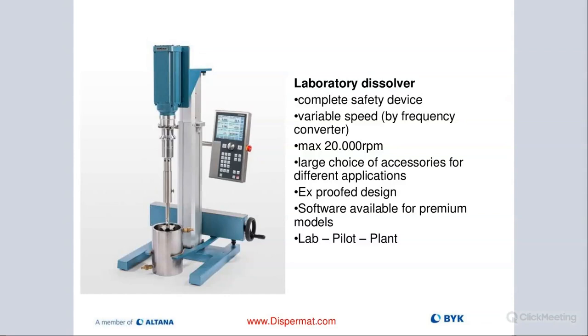And that will be covered in more detail in the second part of that presentation when we do the media milling deep dive. But here is an example of a laboratory dissolver. This is actually our flagship machine, the Dispermat AE. It has a number of safety features. Very important is that H1, H2 setting. It's the working threshold in the container. These are settings. You have an upper and a lower threshold that allows you to safely operate the Dispermat at high speed in between those two ranges.